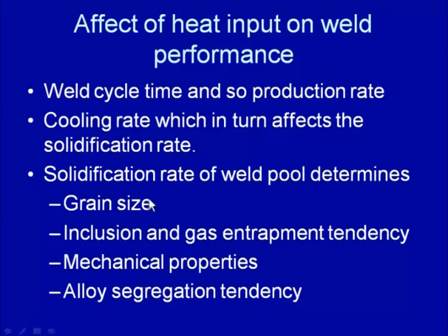However, the inclusion and gas entrapment tendency increases with the increase of solidification rate, because the high cooling rate decreases the time required for solidification of the weld metal.